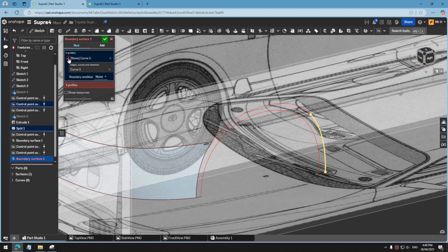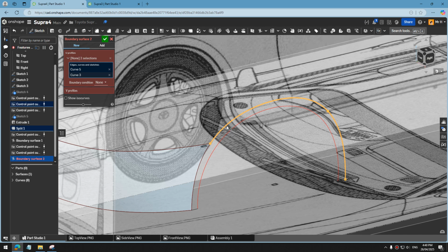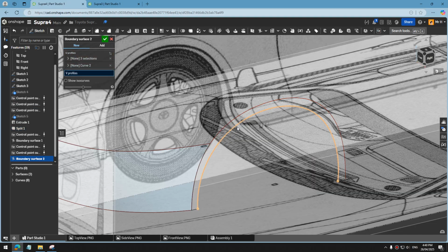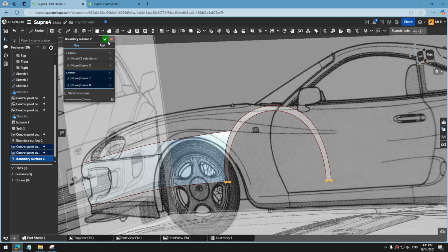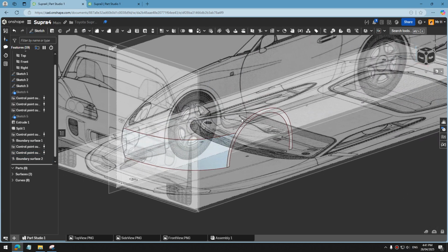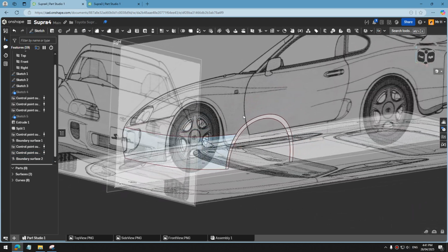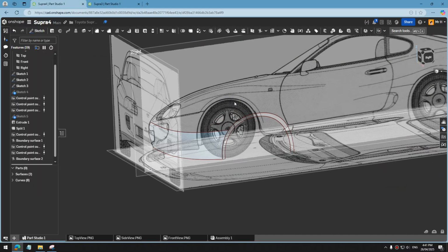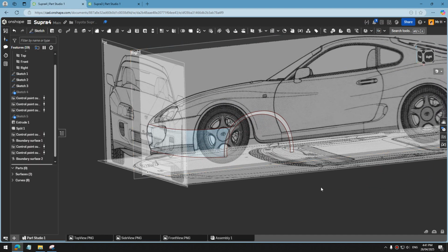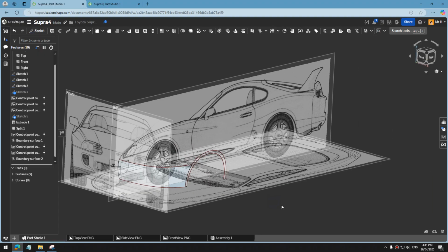We're going to go in here, open that up, click on here, and we can click on the connecting lines. And then we go back to U and we click on this line. So we've got this line and this line. Alright, in V we click on the 2 short lines. Alright, there you go, that's another surface. Click F to bring it to the middle.